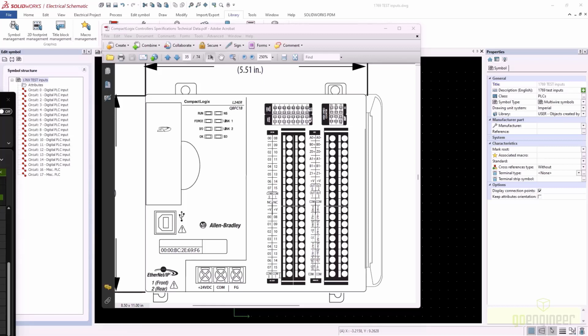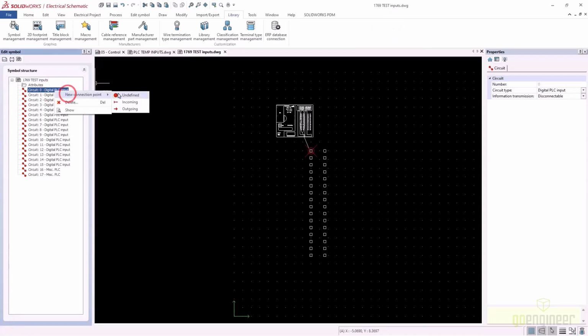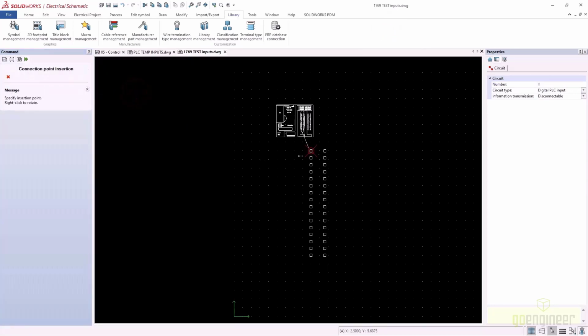It looks like they drop at 8, so it's 0 through 7, and then it's COM 0, and then connection 8 is at the top on the second row, and then stops with COM 1 for the digital inputs. Oh, so I've got to make a little bit of a change here. So this is the perfect time to use that data sheet to make sure on how it's laid out.